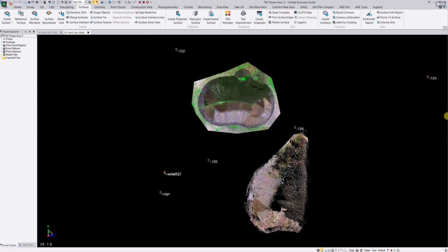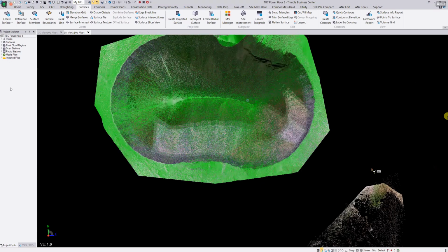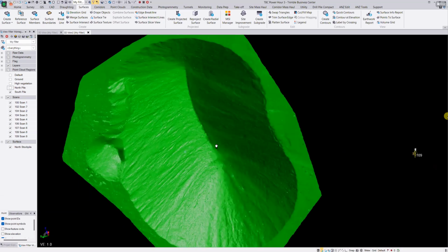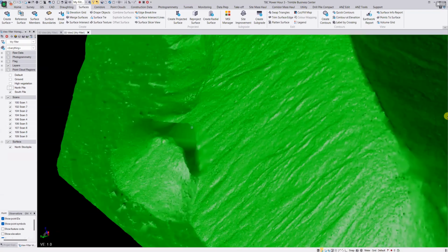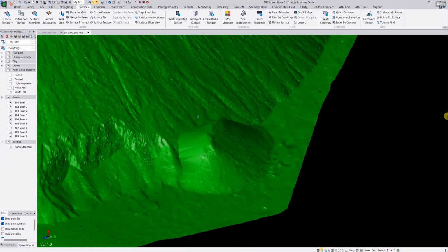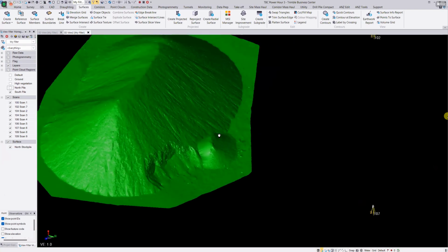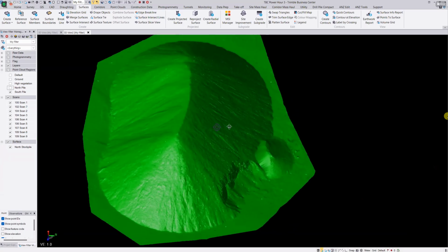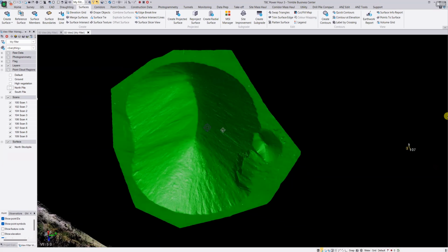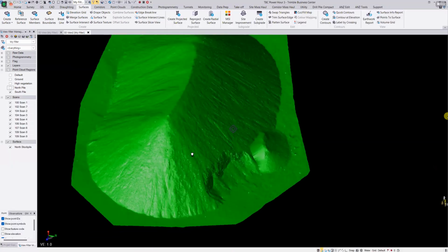There we go. And as soon as I switch off the north pile points, as you can see, we do have a very nice clean stockpile. One thing the guys that have done quite a bit of scanning would have noticed, this part over here. Always be careful, guys, for scan shadow. Obviously, the scanner was this side of this little pile, and it never got any of the points behind it. So that can always be something that tricks up your stockpile calculation as well as your scan work. Always be aware of this shadow that can be generated by an obstruction in front of your scanner.